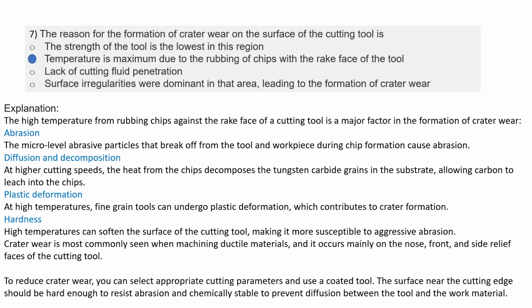So the high temperature from rubbing chips against the rake face of a cutting tool is a major factor in the formation of crater wear. And these are some of the mechanisms which are responsible for the wear.